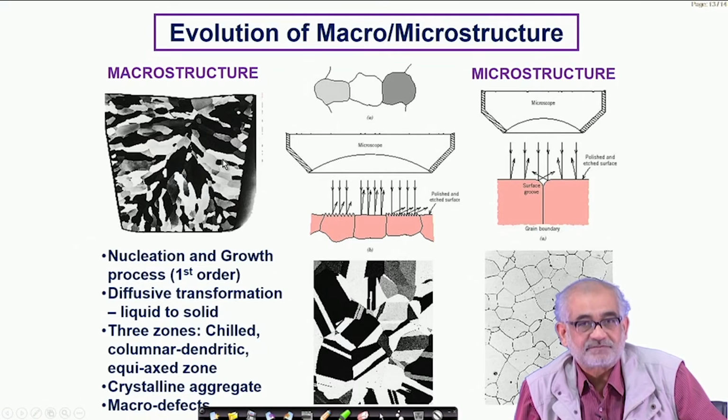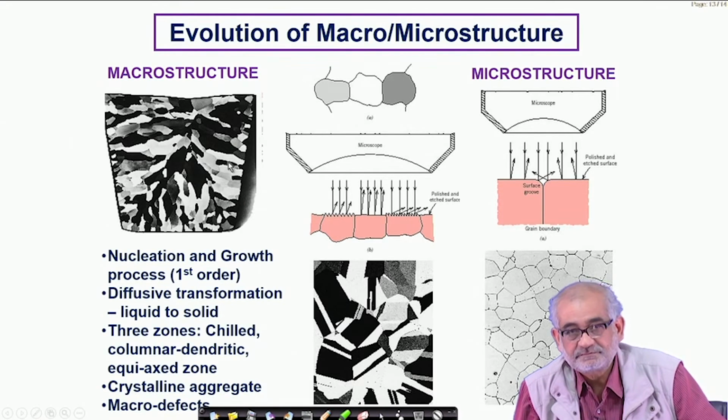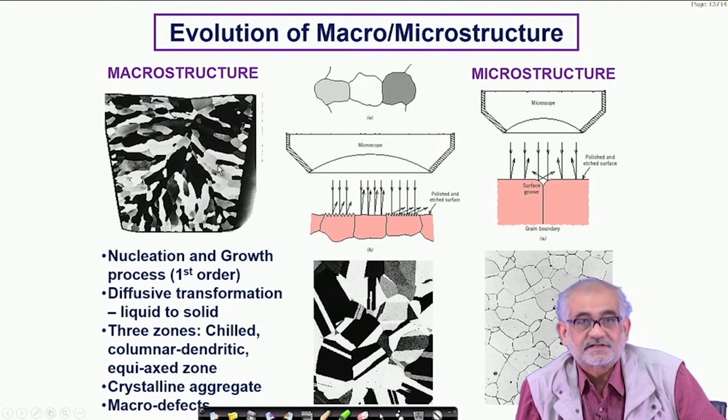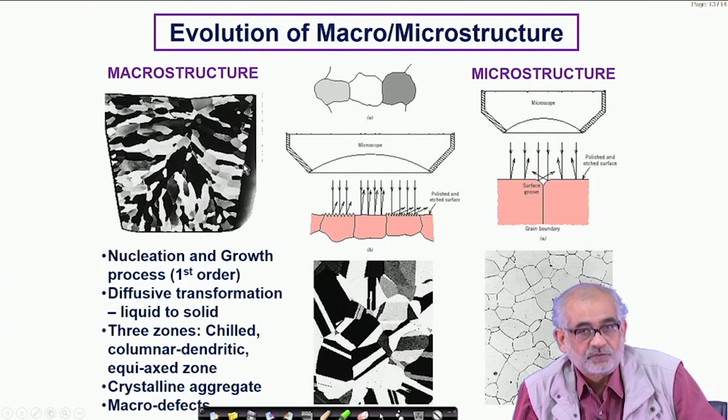At least what is apparent to us now is by color. The question is, where is this color coming from? This color is because of differences in orientation. Orientation of what? Orientation of the crystallites which are growing from the walls. And if the orientations differ, because of their crystalline nature, they carry different densities of atoms as manifested on the cross-sectional plane with which they coincide.